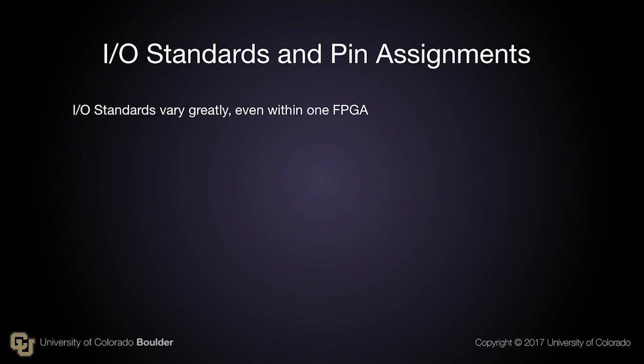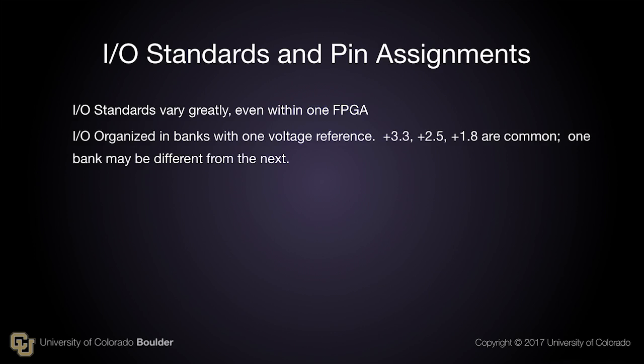I/O standards vary greatly, even within one FPGA. Although the wide variety of I/O capabilities and characteristics in FPGAs allows for great flexibility, it creates challenges in keeping track of all the I/O assignments. I/O is organized in banks with one voltage reference for each bank. 3.3 volts, 2.5 volts, and 1.8 volts are common.